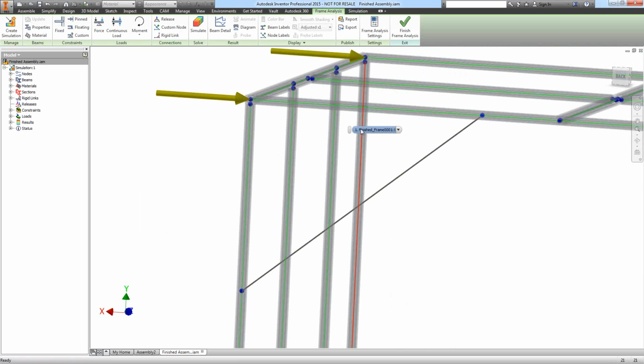Question: if sharing Content Center files between 10 designers on a company server, will I experience a significant slowdown of loading versus the Vault method? My guess is no. People are going to be hitting those files somewhat infrequently. Unless all 10 people did nothing but place content all day, I can't imagine that you would see a significant difference in performance one from the other. They've optimized the Content Center pretty effectively too. It caches a lot of data, so I don't think you would have any problem.